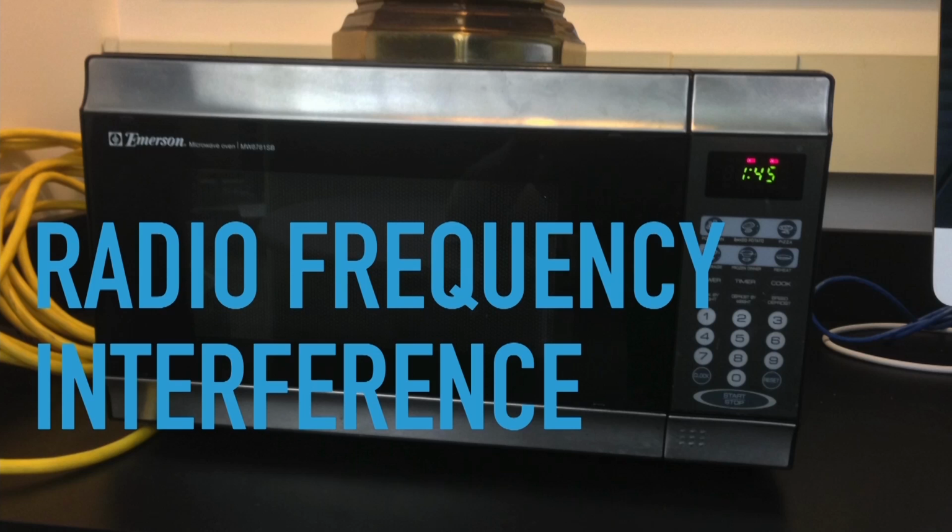And then for our final common problem, we have radio frequency interference. How many of you have heard that microwaves interfere with Wi-Fi? Hands up. Okay, you've heard that microwaves interfere with Wi-Fi. It's a little more specific than that in the sense that in Wi-Fi we use a 2.4 gigahertz frequency band and a 5 gigahertz frequency band. There are a lot of common consumer devices that also transmit on the 2.4 gigahertz band. It's not just microwave ovens.